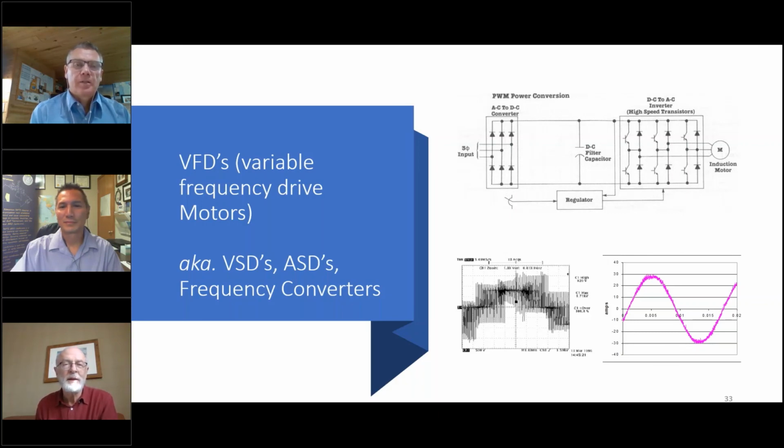I would just add, if you're running some critical equipment and it's tested at 50 hertz, it might do something different at 60 hertz. The motor may be fine, but your driven equipment might behave differently at 60 hertz because of the different speed it's running. So you would be good to specify that you want your equipment tested at 60 hertz speeds, particularly if it's coming from a country where they normally run at 50 hertz.